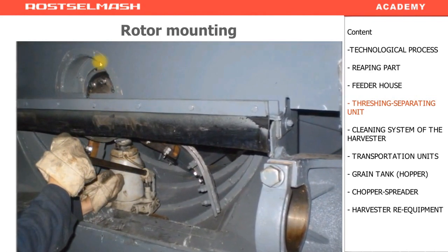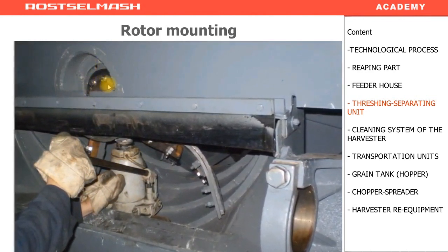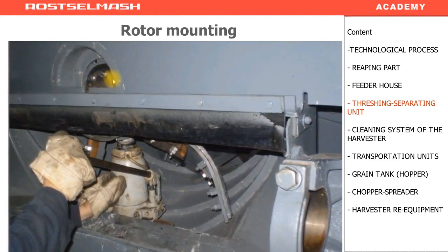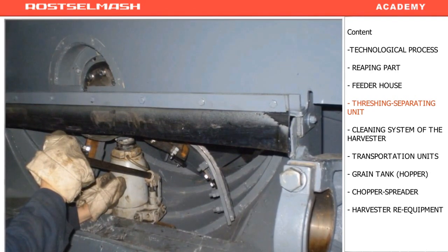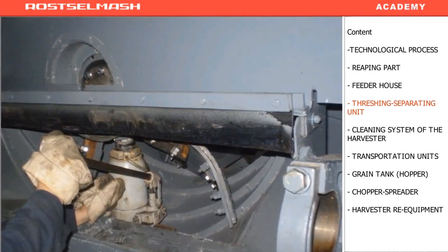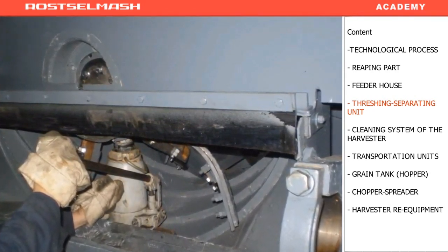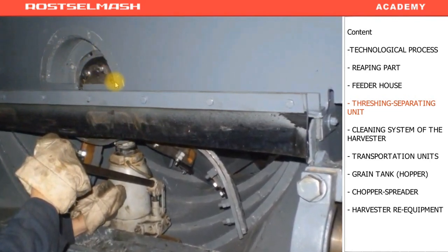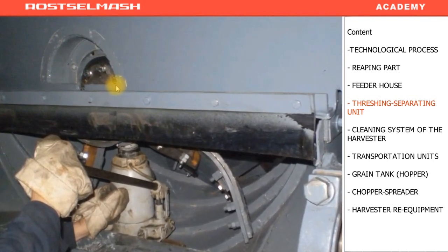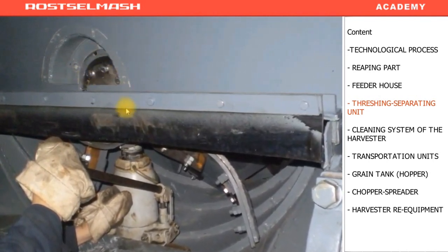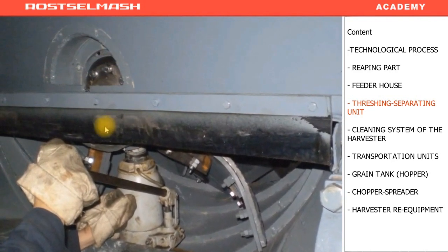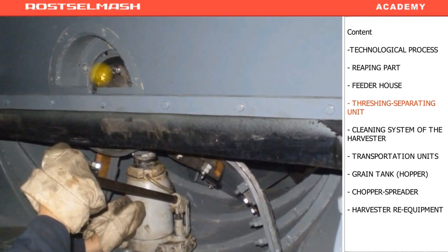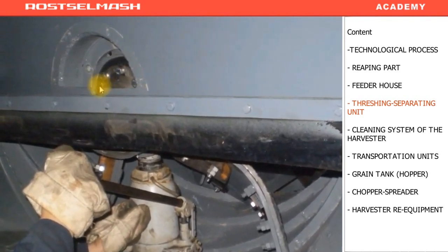When mounting the support bearing, don't forget, it has two greasing points, one for the bearing shell and one for the bearing itself, and there is also a clamper. The clamper must be located below in such a way that the support points are above. Otherwise, when you open the window, and if you forget about the greasing points, you turn it, lock it, and then you find out that the greasing points are somewhere below. This will make it almost impossible to maintain the rotor support.